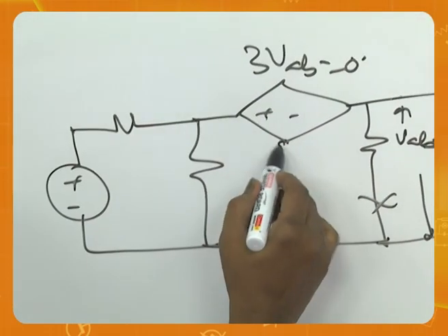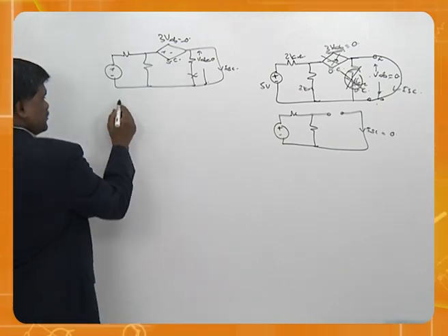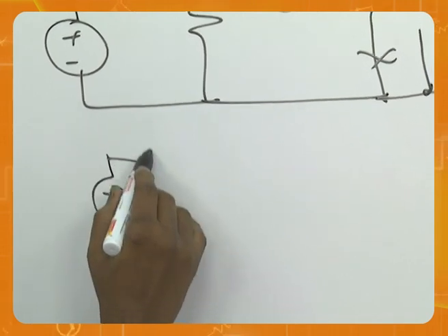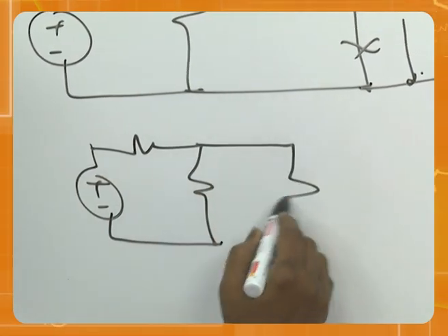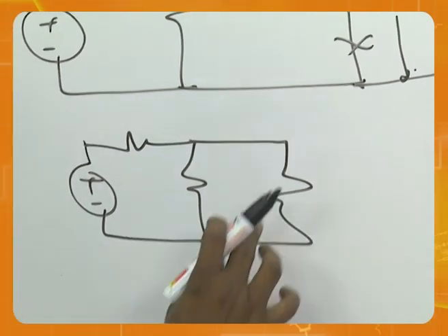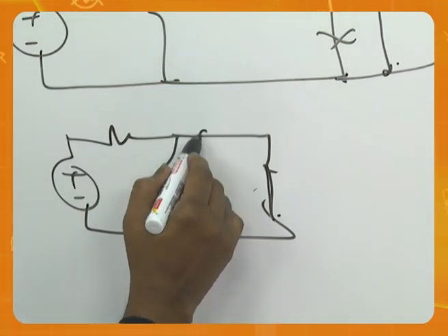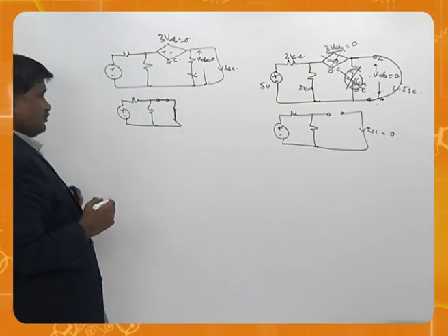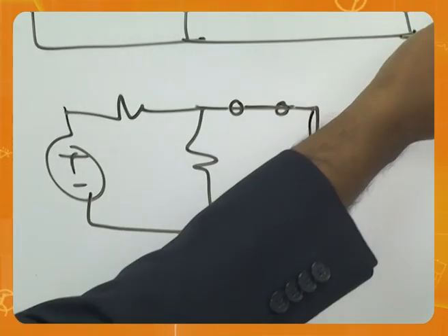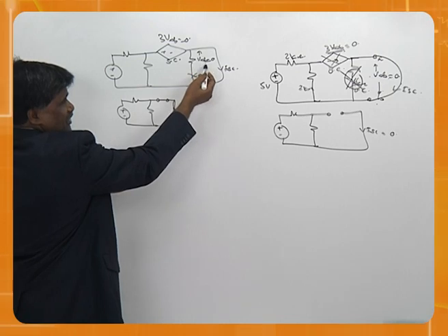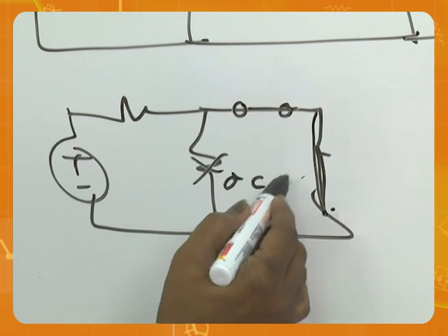When a voltage source is 0, it means short circuit. Then I will draw the equivalent for you. So, this is the voltage source. This is shorted, and this is shorted again. So please remember this is short circuit. And when this is short circuit, because of this short, this became 0, because of this became 0, this also goes. So this is also open circuit.